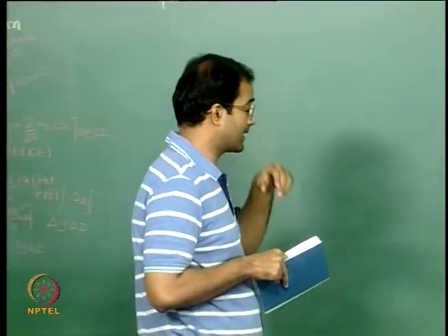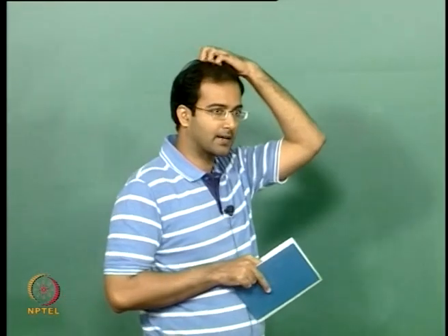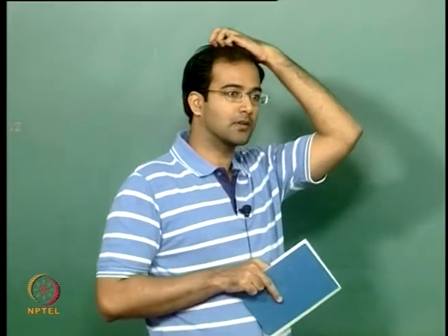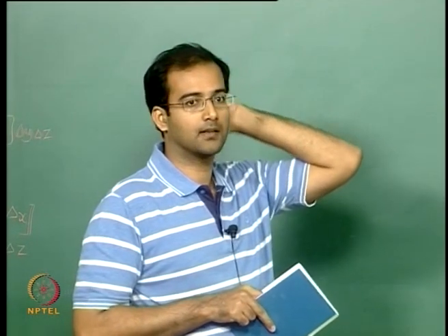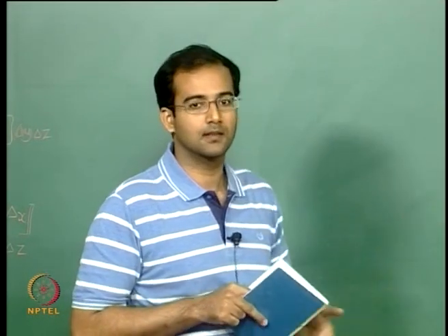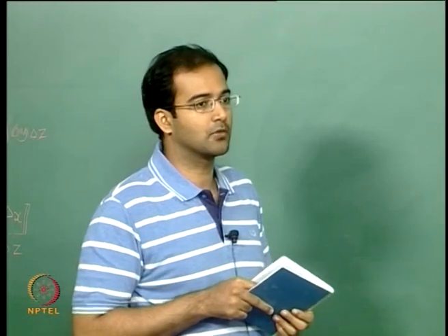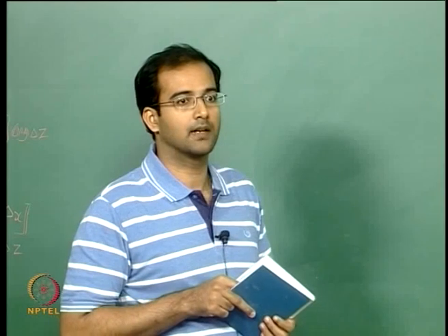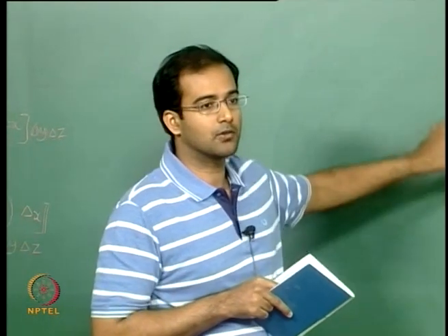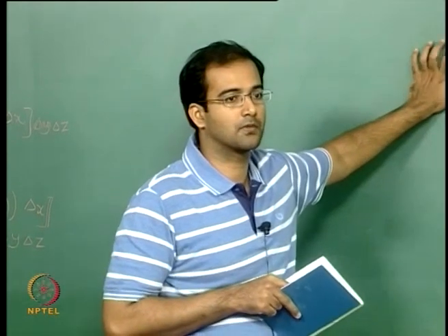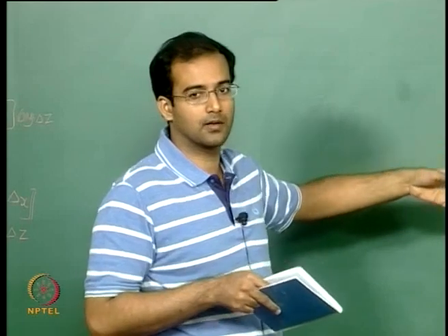We first have to use some relationship between the stress and the strain rate: Newtonian fluid approximation first, and of course the Stokes hypothesis. For a compressible fluid you would derive more terms, but we are more interested in incompressible fluids in this course, so I am directly going to substitute the Newtonian fluid approximation for incompressible fluid, because otherwise we will accumulate more and more terms.